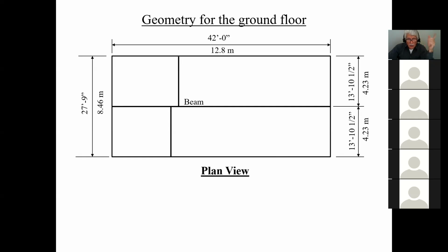So basically, what I do in the back of my mind is this, okay? I say to myself, I want to stay at approximately 12 feet spans, right? I have 42 feet, and therefore this is about 3.5 spans. So instead of just having 3 spans of 14 feet, I would maybe look at creating 4 spans.